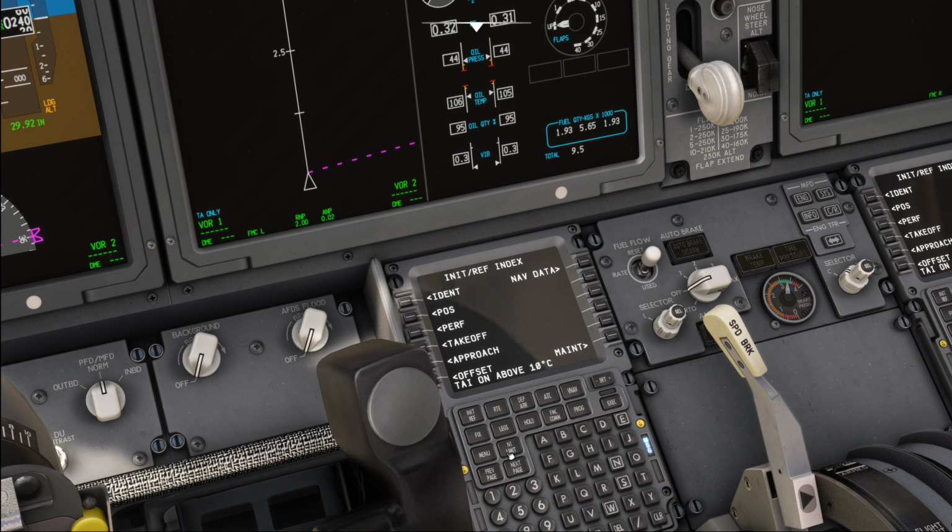On the airplane that we're in right now, we have a 28K engine installed, but it is also available in 27K and 26K, which is technically just the software derating the aircraft, rather than any actual physical changes to the engines. Together with the new engines, there have also been updated electronic engine controls installed on the aircraft, which incorporate 2 new automatic engine shutdown functions.